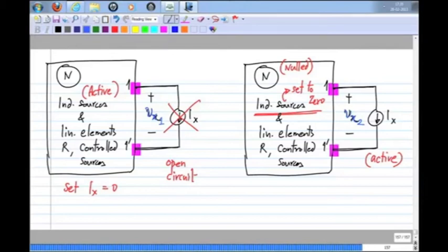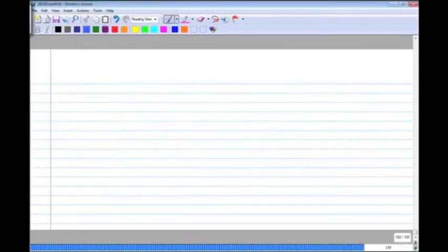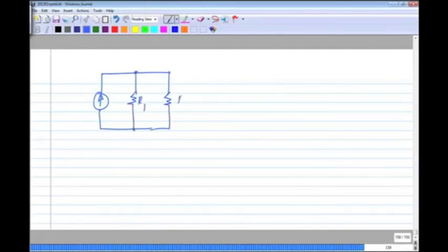And the next thing is about current division. Now, current division is the counterpart of voltage division. I will show it with two resistors, R1 and R2. Clearly, if you have two parallel resistors R1, R2, the voltage across them will be the same. Let me call it Vx, and the current through this will be Vx by R1.